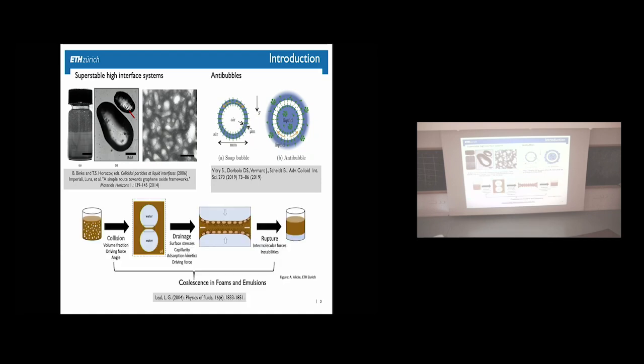And then, of course, there's coalescence that we want to influence in foams and emulsions. When I bring two interfaces together, the stress boundary condition here dictates the flow in the thin liquid layer. If there is only surface tension, the interface cannot carry any tangential stress. If there is stuff, in this case particles, that interact laterally, and I form a skin, I form like a pipe. There's a solid wall, and I have slower flow. And so drainage is an important step.